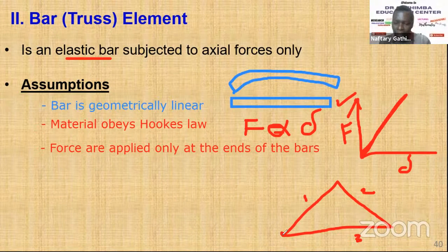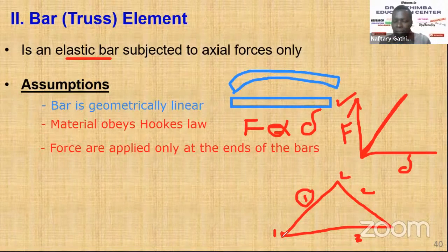So this element here goes from this node, let's say node 1, to node 2, and for the element, we circle the number here to differentiate it from the node. The member, with node 1 and node 2, defines the domain of the truss element, one of the members of the truss structure constituted of all three nodes. So the element is just one member, and that's why we also refer to it as the truss element.